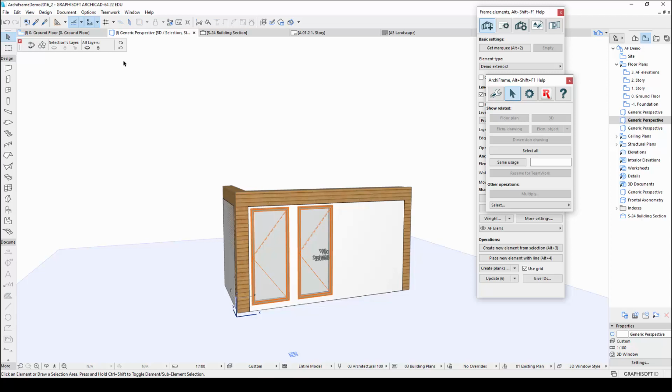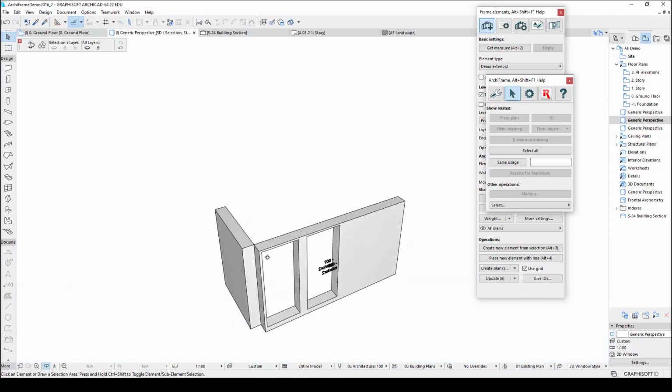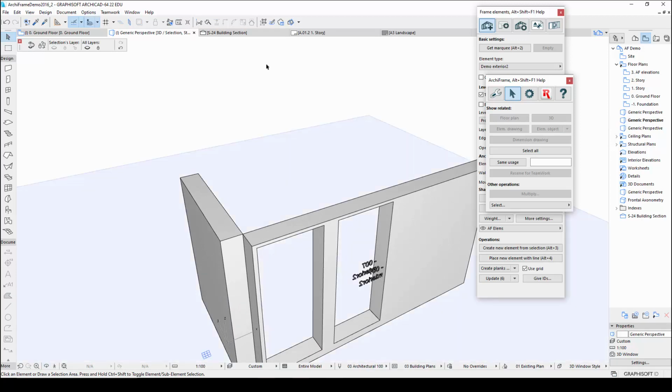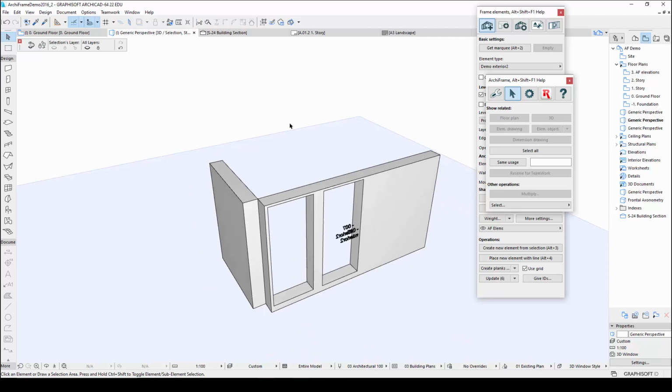Once the architect has defined the size and position of the openings, the engineer does not have to redefine these in the engineering model. Also note that the wall elements are very simple, with each layer in the wall only consisting of one object. In other words, we have not yet created all the individual studs and boards that the finished wall will contain. This is because I still need to customize the shape of these walls a little bit, and it is easier to edit a simple wall than to adjust each of the numerous pieces in the finished wall.